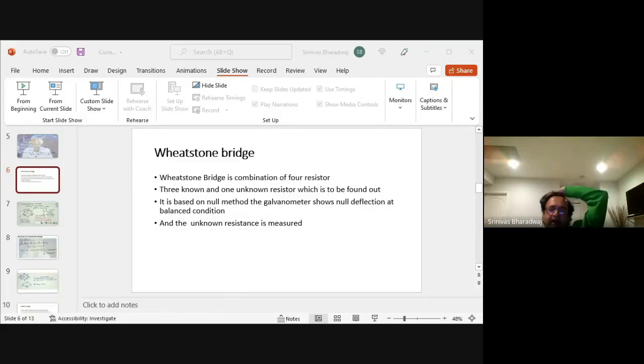Now, once you have measured the gradient, E exactly matches the gradient of a portion of the length. And when you need to measure the internal resistance, you close the second switch K2. First, you run it without K2. You leave this one open so this R doesn't come into play. If you leave the switch open, the R will not come into play.